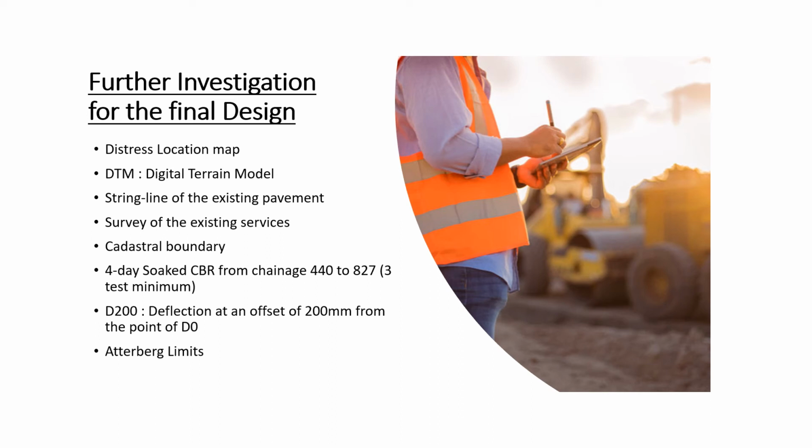This is where we get the maximum deflection, where the CD is more than our design deflection. So maybe we can suggest extending the pavement over the shoulder and also improving the drainage in this area. Also, we need to get the Atterberg limits to check what material we have on site and what sort of pavement we have.